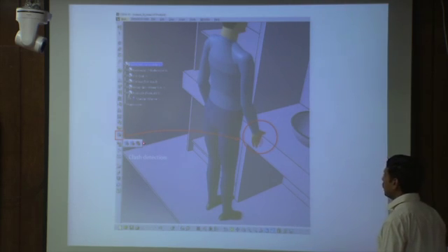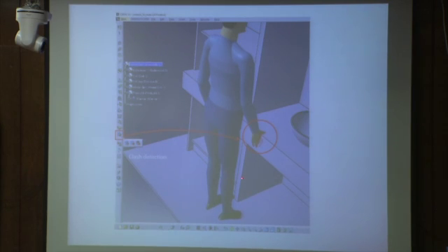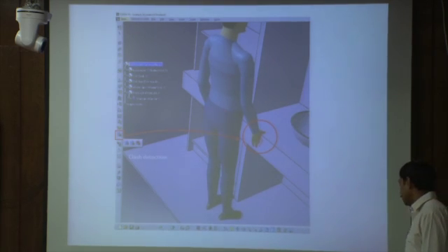And there is this type of option: while you are moving the human model from this side to this side for positioning it properly, if it collides with the product, then it will restrict the movement. So this type of tool is also there. Further you cannot move forward, because if you keep it on, then while you are moving the human model towards the product or facility, whenever there is a collision, it will stop the movement. It means that is the final position, it cannot go beyond that. Otherwise there will be some interference.